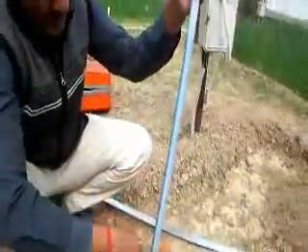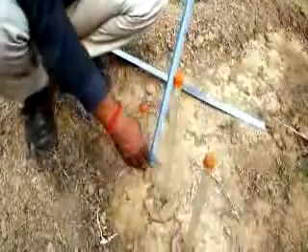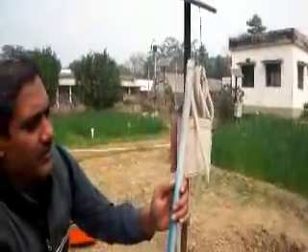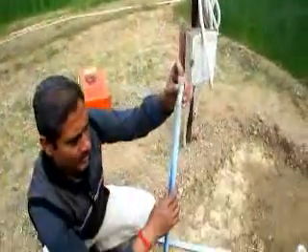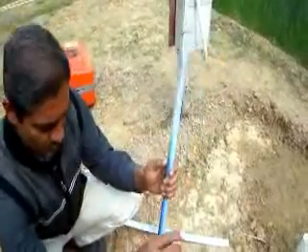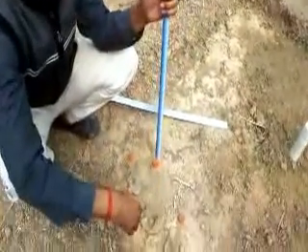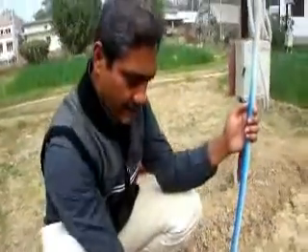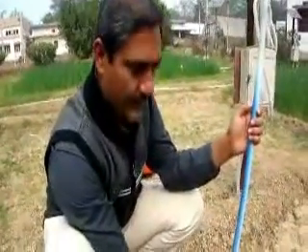Once water gets out from this porous cup, it creates a suction in the tube. If we measure this suction, we can find out the suction condition, or hydraulic head, of the soil at the depth where we installed the porous cup.